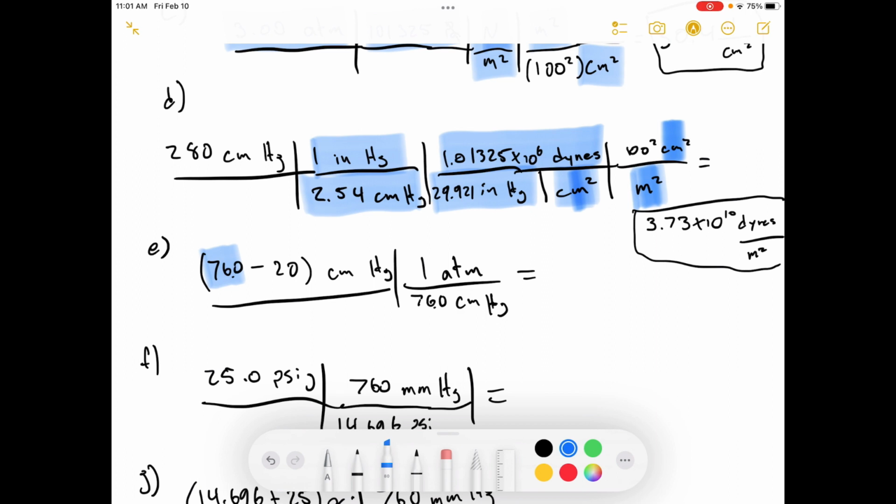There's 76 in 1 atmosphere, and we do 76 minus 20, so that is the actual pressure, not the vacuum pressure. It's the actual pressure inside of whatever this vessel is, and outside the vessel we've got 1 atmosphere. Inside the vessel we've got slightly less than 1 atmosphere. We've got 20 less than 1 atmosphere, so that's what the pressure is in the whole vessel altogether.